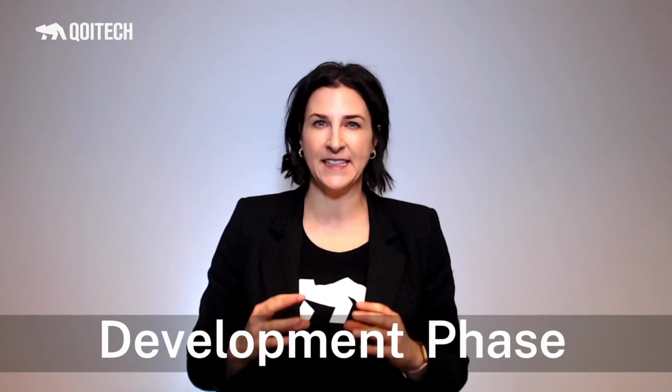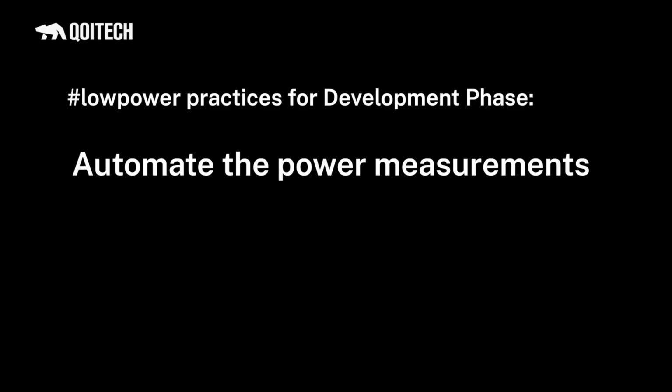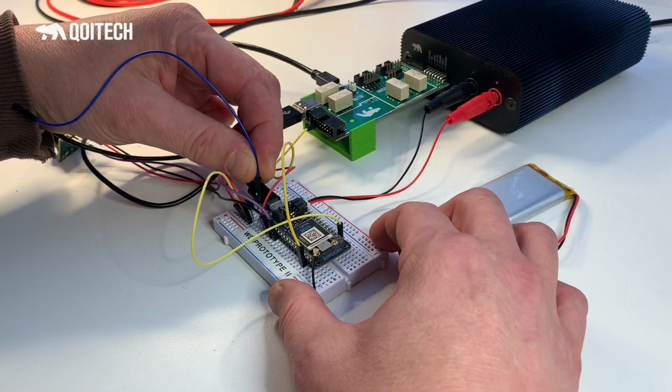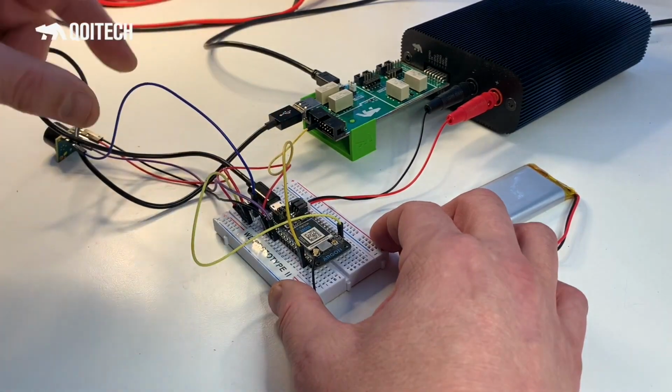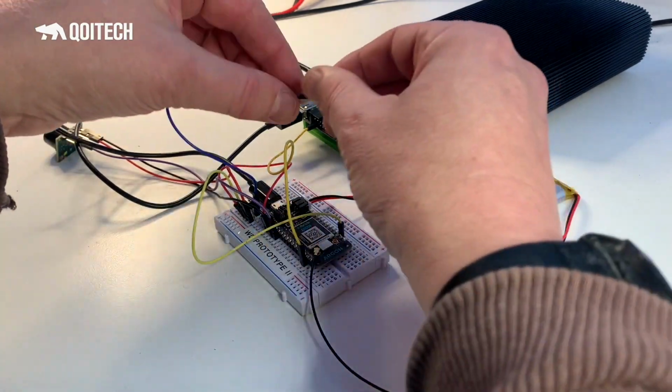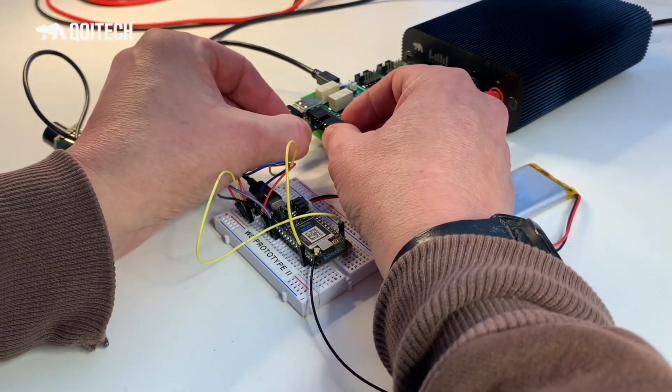Practicing low power mindset in development phase means the following. Automate your power measurements. Development is an iterative process, and your energy optimization will depend on whether you have included power measurements for each of the iterations made, whether they be in hardware, firmware, or software. This is no different than having automated tests to find firmware and software bugs to detect performance degradation, high memory